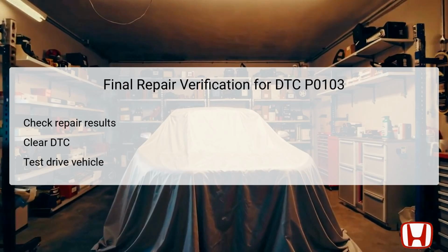Firstly, examine the repair results based on the continuity checks and any component replacements. Once satisfied, clear the Diagnostic Trouble Codes, DTCs, in the ECM/PCM using the HDS tool. This action resets the system and prepares it for any new diagnostic checks. Finally, conduct a test drive under various conditions to assess the vehicle's performance and determine whether the DTC P0103 reoccurs. If the check engine light remains off and the vehicle operates smoothly, the repairs can be considered successful.